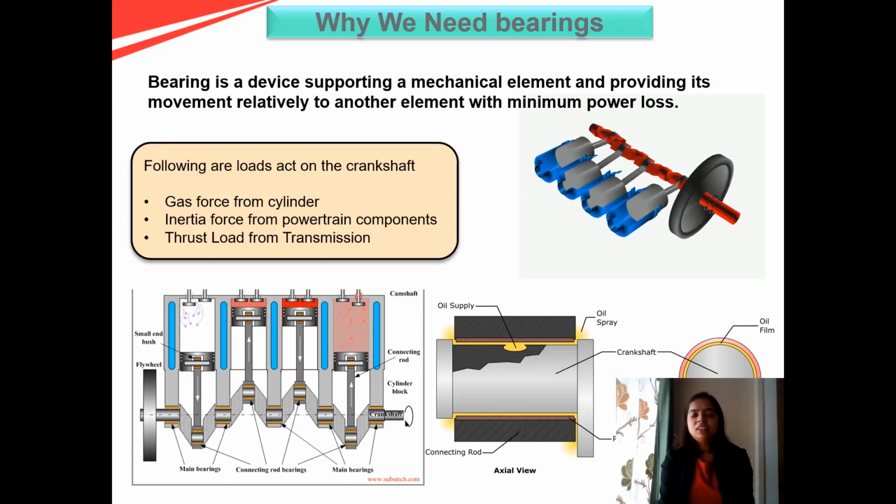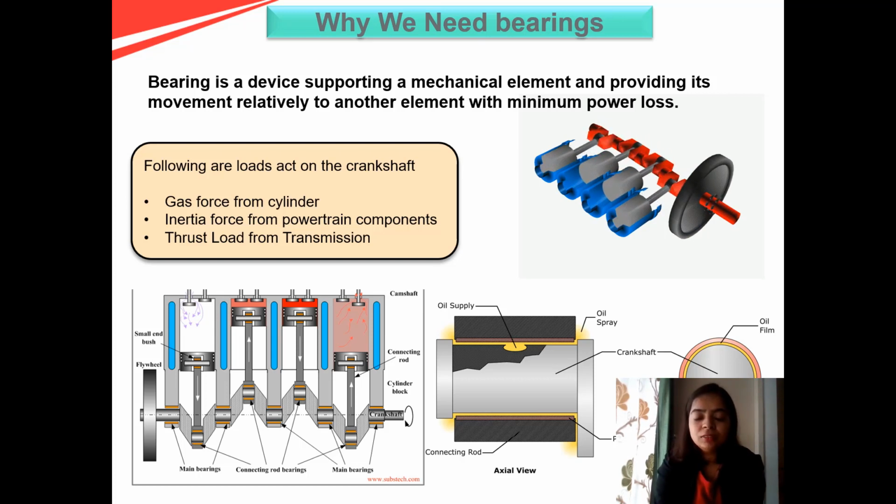Bearings are the components that assist the motion of a component sitting on a stationary component. In our engine, rotating movement of crankshaft and camshaft are taken care of by bearings and bushes. These bearings and bushes form a thin layer of oil in between crankcase and the rotating component, thereby reducing the coefficient of friction and assisting the motion.